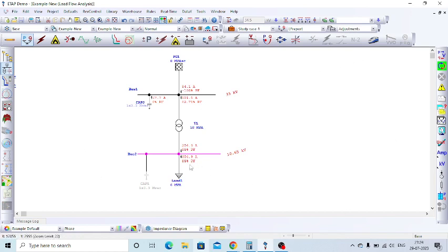Earlier the load alone was operating at 85 percentage power factor, but the branch circuit, that is the transformer circuit, was operating somewhere around 99.9 percentage. But now can you see, when the reactive power compensation device is moved from the low voltage bus to the high voltage bus, the load is operating at 85 percentage.